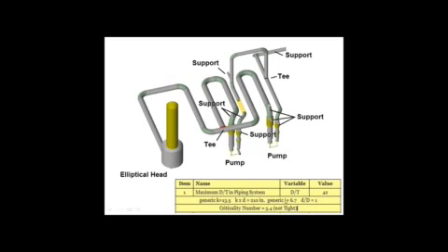Piping is, okay, that's a pretty long length, but when we look away from the T, we see that there are a lot of straight lengths in this. The guy that designed this system knew that he had to put flexibility in to keep the loads off the pumps. So there's a ton of straight pipe here in the loaded directions. So these are definitely not tight piping systems.